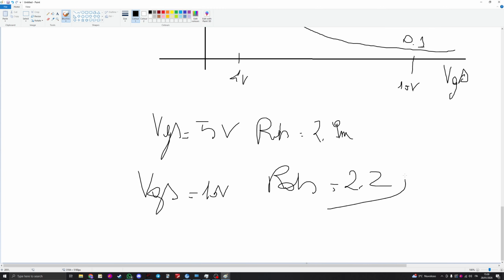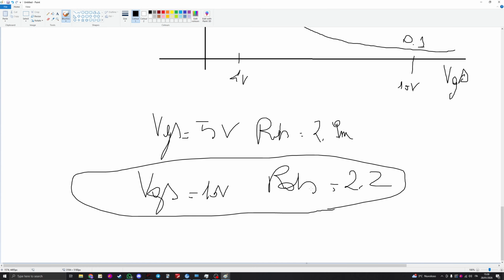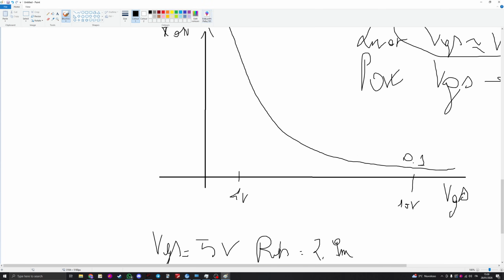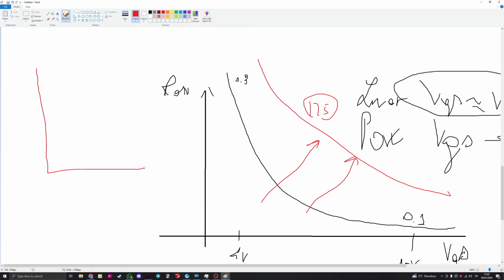So in this case you are gaining more and more efficiency for free, because it costs you nothing to raise the voltage of the gate. But be careful, because in this plot of the resistance, when the temperature is higher, this resistor heats up, and the resistance doubles, R0 equal to 2R, when the temperature is very high, like 150 degrees.